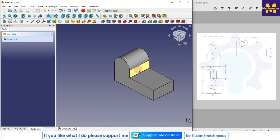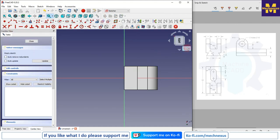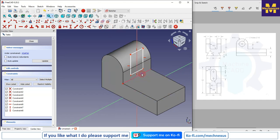So for this I will select this face and I will create a sketch and I will set to the isometric, and I will draw a rectangle on this face, and then we will read the dimension. So I will project this edge, I will select this point and line and make it coincident, and I will make it symmetric.